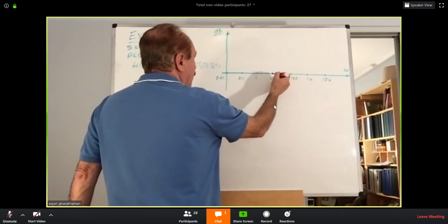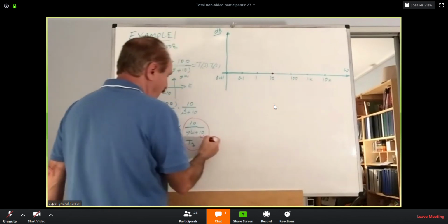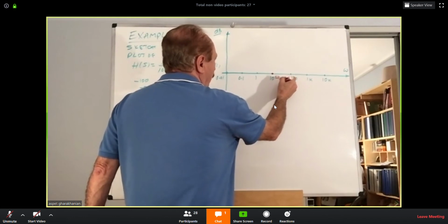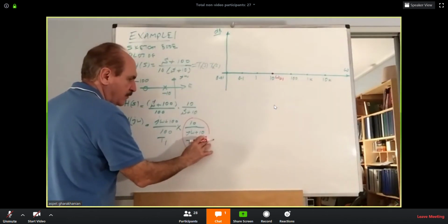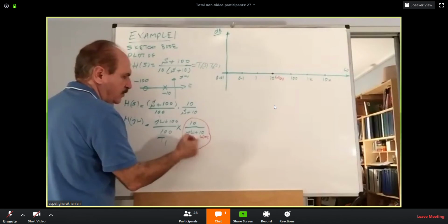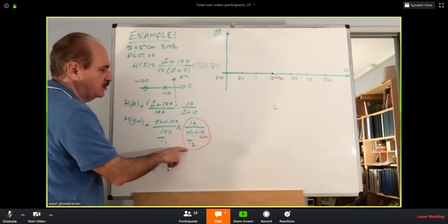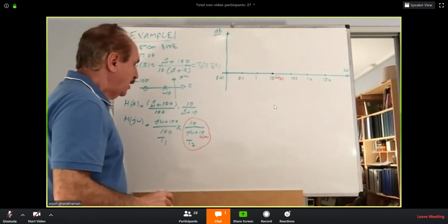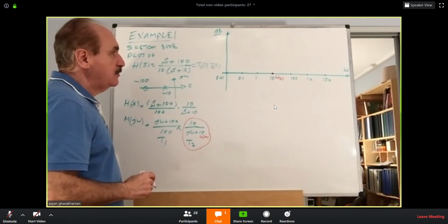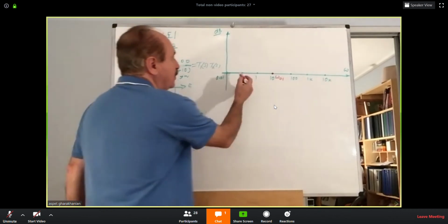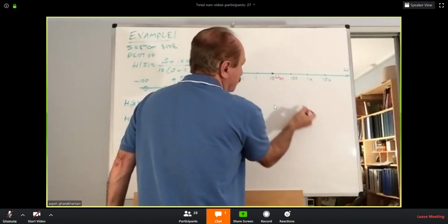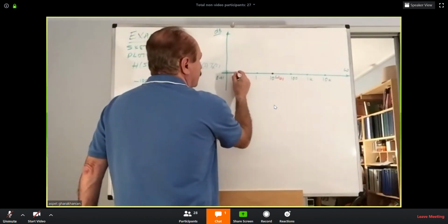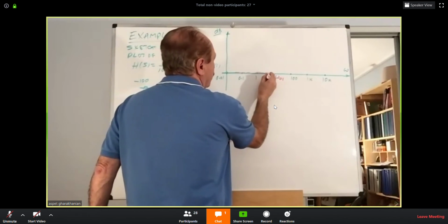This is your omega O of 1, let's call it. That's the cutoff frequency pertaining to the pole of transfer function T2. All right. Now we know how their poles are going to look like. They're going to be horizontal, and then they're going to slope down. Now, horizontal, constructed all the way to here.